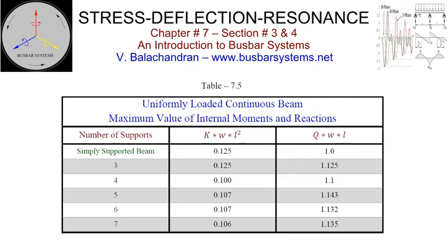A conductor supported on 2 insulators, or 1 span, can be approximated to a simply supported beam, whereas if it is supported with 3 or more insulators, 2 spans or more, then it can be approximated to a continuous beam. Short-circuit generated electrodynamic forces on the busbars is considered to be a uniformly loaded beam with multiple supports. For the solutions to such a problem, the theorem of 3 moments is applied.